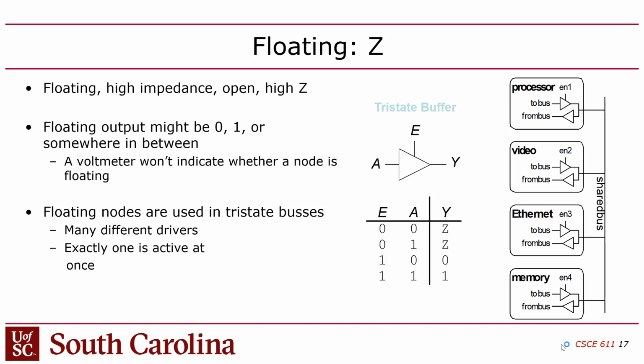By the way, you may also hear about this thing called Verilator, which is kind of a cool tool. You might come across this. Verilator is an open source package that you can get in Linux and Windows, and it will take a Verilog file and convert it to an executable format so you can run it, which is kind of neat. It's a useful tool, and it's free, unlike the ModelSim that we use in this class, which is commercial and expensive.